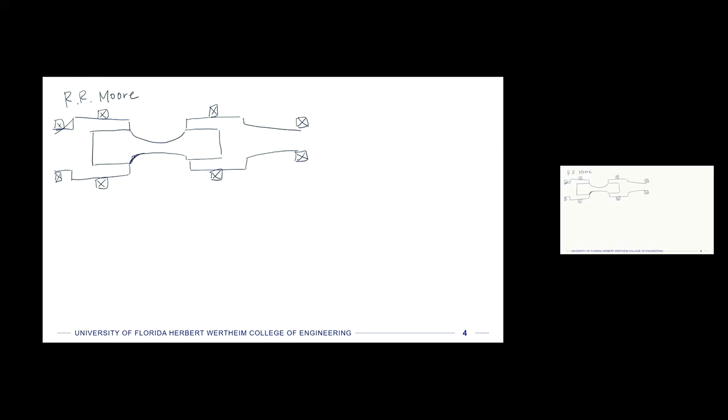There is this specimen in the middle that a force is applied to in some kind of way, and this could be a hanging weight with another bearing. It could be a side displacement applied by something also with a bearing, but there's a side load here in the middle, and then this entire system is rotated.